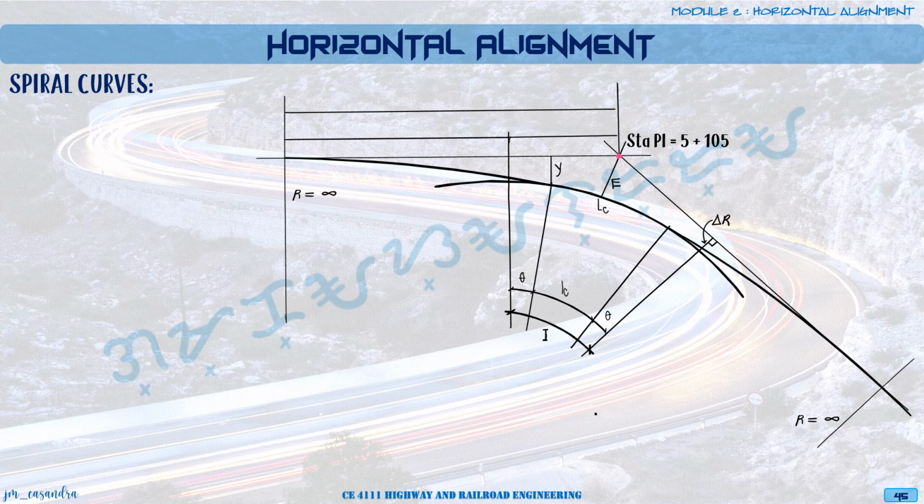Okay. So once we have computed our TC, we can now write the values of our distances in our diagram. For step 5, we have our spiral length, from the tangent to the new start of the circular curve, of 112 meters. We have the reduced arc length of the circular curve, which is 114.